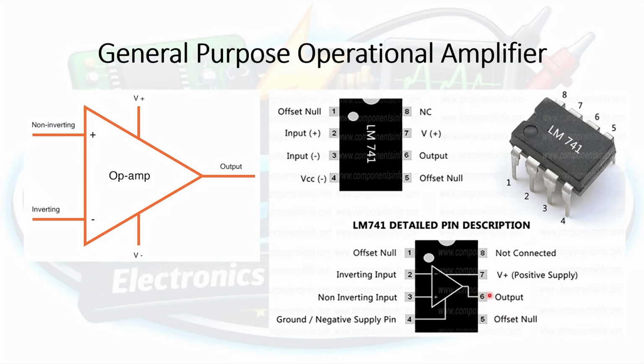It might be worthwhile to take note here that pin number 1, pin number 5, and pin number 8 are not being used. Actually, in some special circuits, you might have to use pin number 1 and pin number 5. However, pin number 8 is never used. So we're actually only using 7 pins. However, for our demo today, we will not be using 1, 5, and 8. We will just be using 5 of the pins of the integrated circuit.